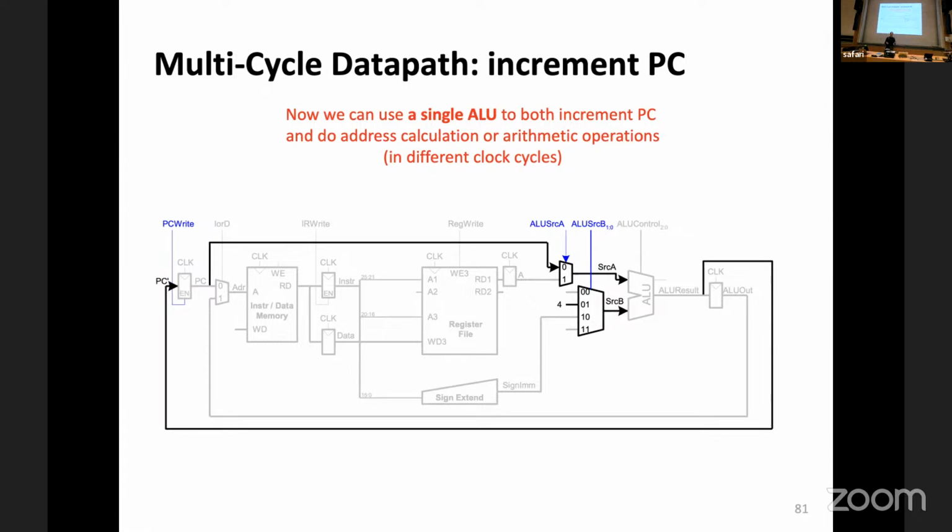So now this is beautiful. We do not have two memories, and we do not need two adders for a load word. And that's the load word. Load word is done. Now let's add to this data path. Is everybody okay with this? Happy with load word? If you can do load word, the rest is relatively easy.